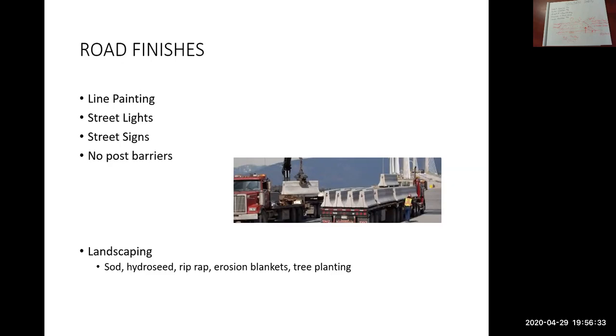So the bases are there already. A street light base can be 1.5 meters tall. You typically only see the top 50 millimeters of it sticking out of the ground, but there's another 1.5 meters that's buried. Sometimes more, depending on the size of the sign or the street light. They're quite large concrete bases.